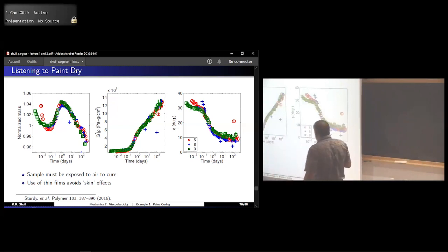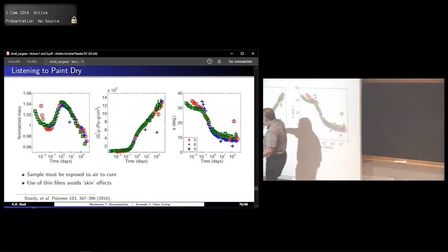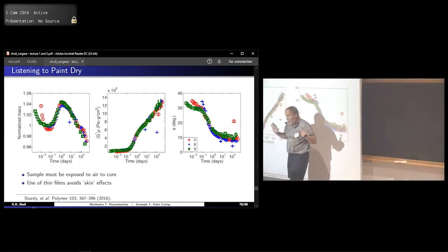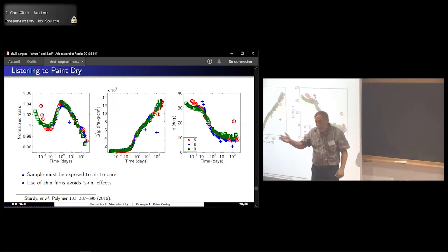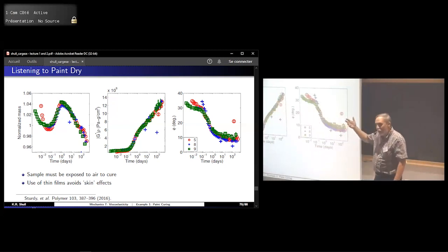Yeah, so the question is about adhesion and internal stresses. I would say by adhesion here it really means wetting. It doesn't need to mechanically adhere well, it just needs to wet well. The biggest problem with some of these things is if it takes a while to cure. The alkyd paint was good because it wets. We don't have any problems. Linseed oil, oil-based films, what Rembrandt was using to paint with, which the community cares about more, is trickier because it starts to oxidize and it de-wets. So you have to do creative things to get it to wet on the substrate.